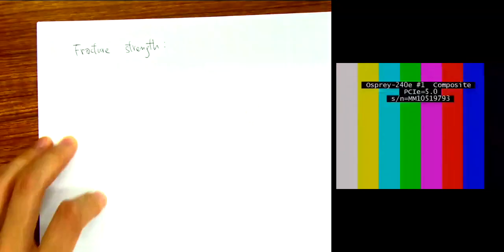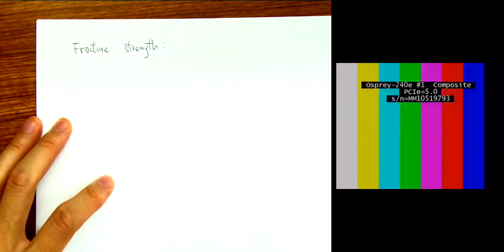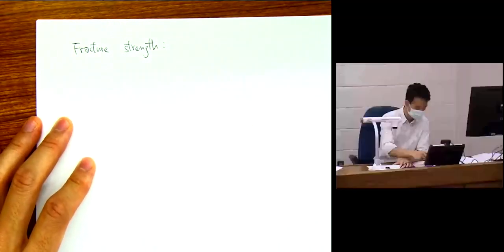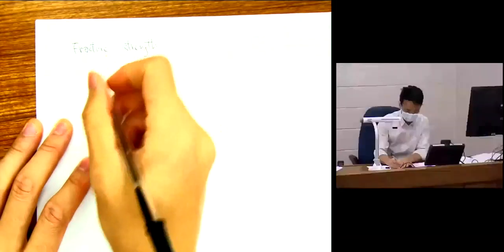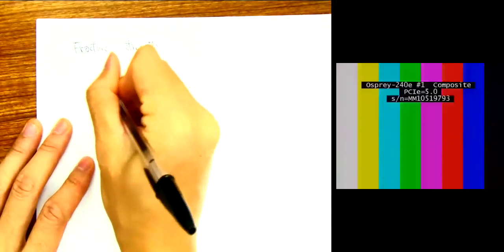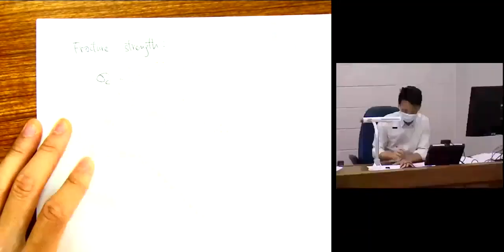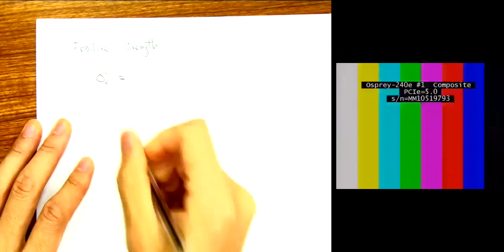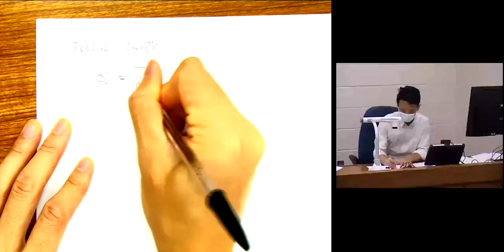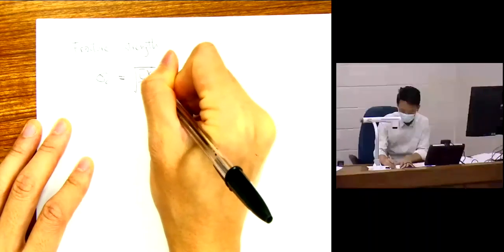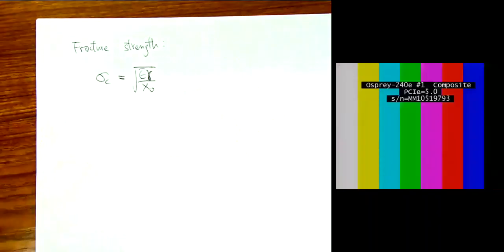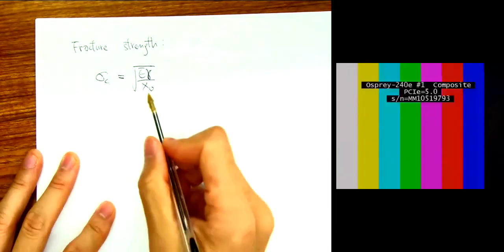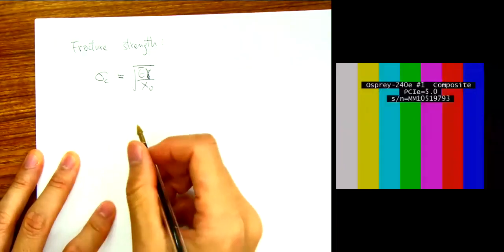There's the concept that we've been using all the time before the time of Griffith. Even though we know there are some fundamental flaws to it, because we did not care about flaw size at that point, right? The first classical fracture strength, I'm going to call it sigma C. Sigma C means the cohesive strength. From atomistic calculation or estimation, it is E gamma over x naught, right? That is maybe from the second lecture, where x naught is the equilibrium distance.